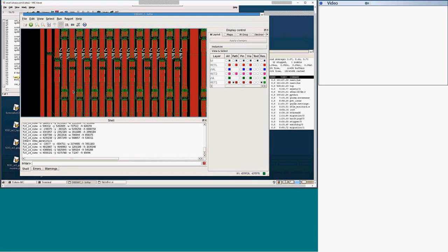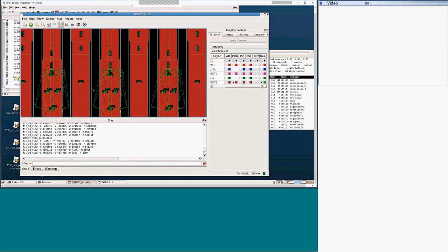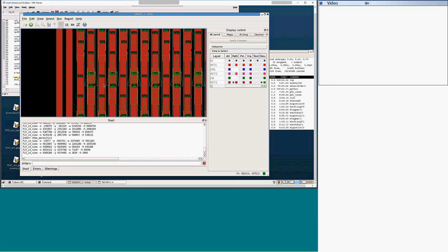So in order to get what you were referring to in terms of the effect of the poly resistance involved in charging the poly from one end to the other end, you extract each finger with segments, sub-transistors, to a finer resolution. Yes, reduced by finger. It would be by finger and by segment within the finger.